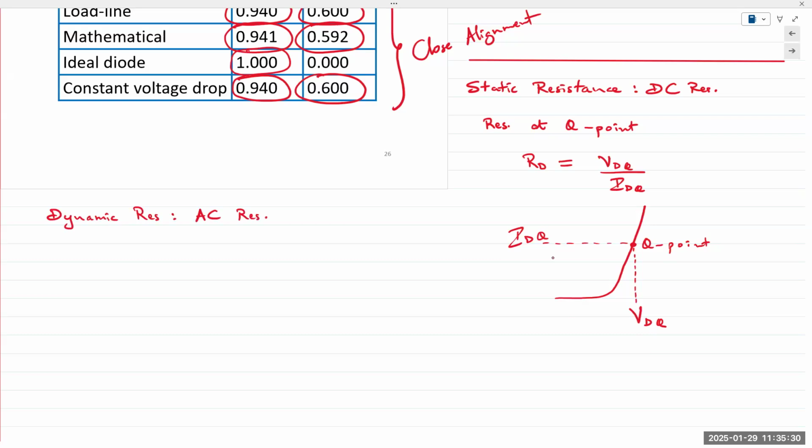And as the name suggests, we pick a point or two points in there to determine our AC resistance. But there's a whole technical explanation that we can't get into in this class. The diode curve is not technically a completely flat or linear line, so there is some curve to it. Mathematically, we can draw a tangent to that point. So we pick a point and pick minor variations of the voltage on either side of that point.